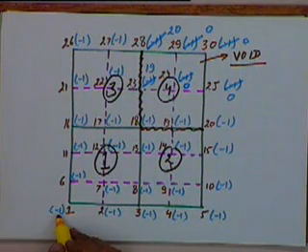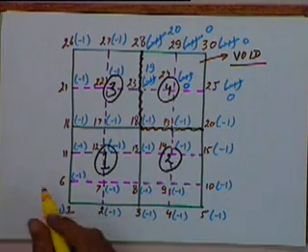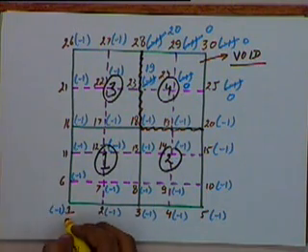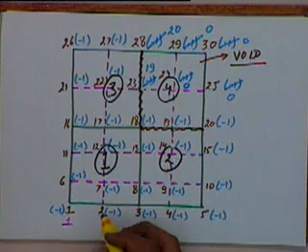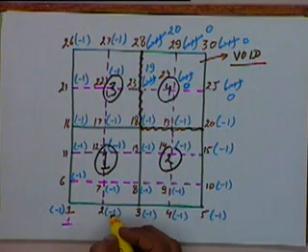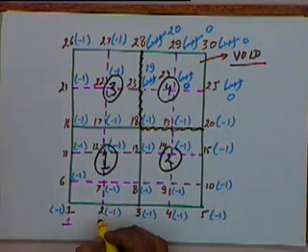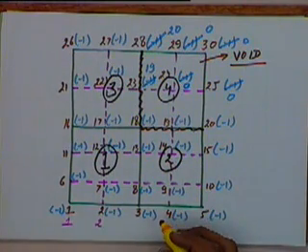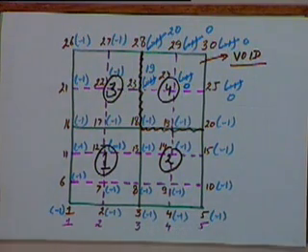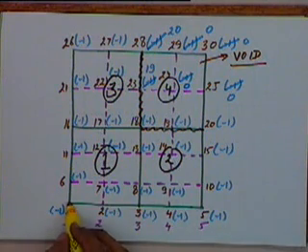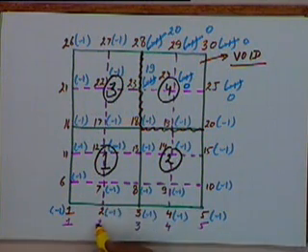If its label is negative, its node number will be made equal to nn. We have initialized nn as 1, so this will take a node number of 1. Then I will say nn equal to nn plus 1. I will come to the second point, again the label is negative, and this will become 2. This point will become 3, this will become 4, this will become 5, and so on. So the node number of this node will become 1, this node will become 2, and so on.